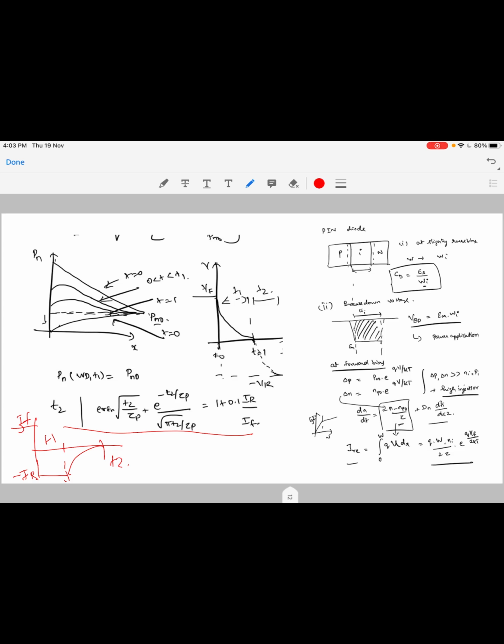This is the reason why whenever you have bulk charge transport characteristics, you will have what is called the charge storage time, and hence it will not allow you to switch so fast. That's why a BJT is not a great device in comparison to a MOSFET, which has a sheet charge density. We also saw some interesting aspects of the PIN junction diode, where the depletion capacitance does not depend a lot on the applied bias, but depends strongly on the intrinsic layer that you have.